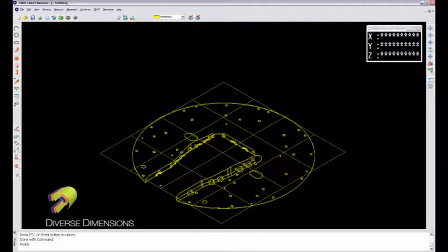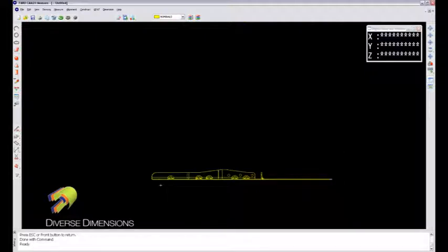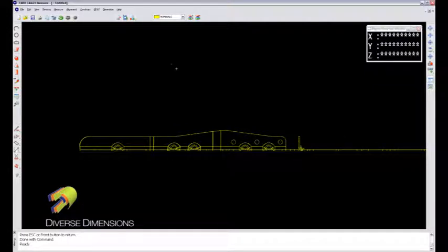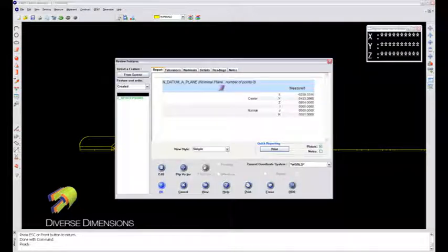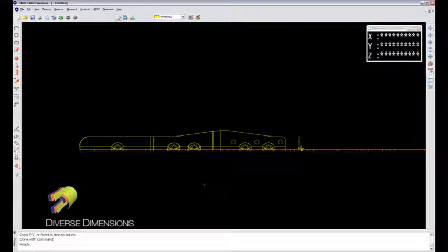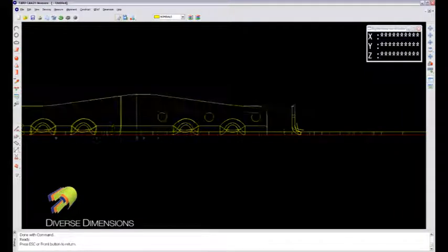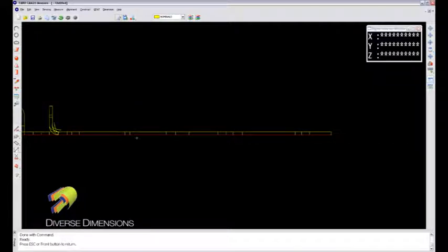Now it's kind of nice if I look from a side view of this object. You can see as I scroll in just a little bit more, and I'll go back to review features a second. In this nominal datum A, I will view it, and just look, it is truly on the bottom of that surface. You see it's highlighted red, and as I scroll over to the right side, it occupies that whole bottom surface. So now you can use this for measurement of a constructed coordinate system to blend it to your CAD model.